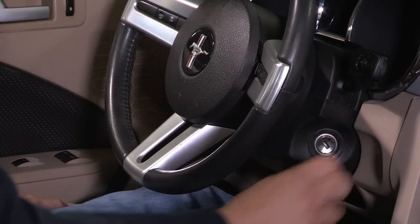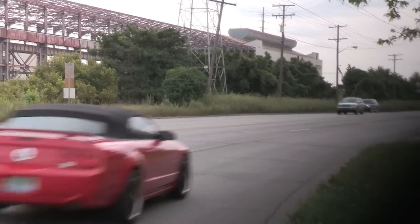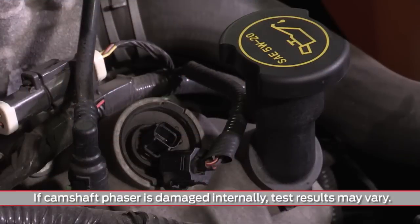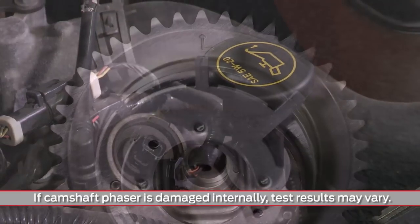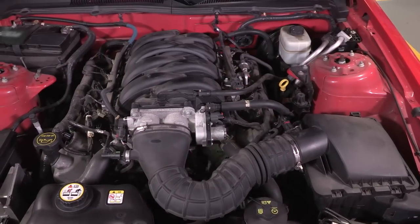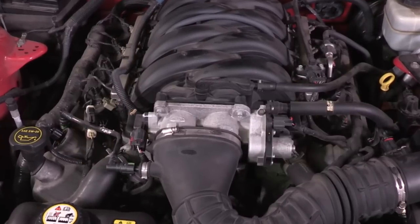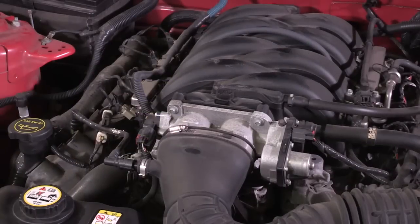Turn the engine off, and electrically disconnect the VCT solenoids. Then take the vehicle on a road test. If the engine noise is gone or changes, it suggests a VCT issue. This diagnostic step can be effective because disconnection of the VCT solenoid will lock the VCT phasers in place. It eliminates a lot of other systems that can cause the same symptoms, including the fuel delivery, ignition, and some base engine concerns.